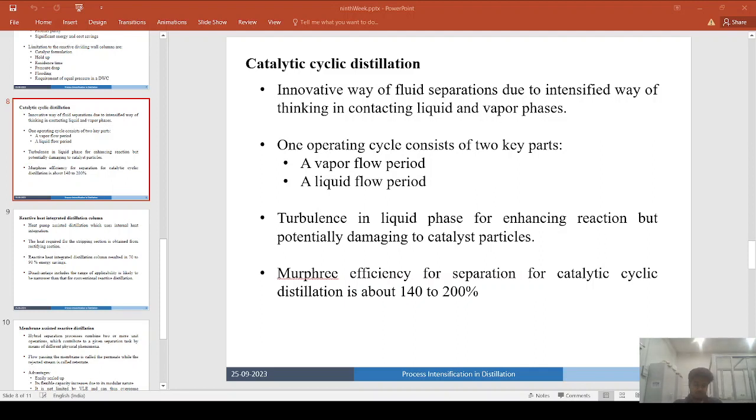because if there are high pressure ratios between those two, the heat that is released from the rectifying section may not be beneficial for the stripping section, because that heat may be coming from a very low pressure zone, so it will not be of sufficient quantity.